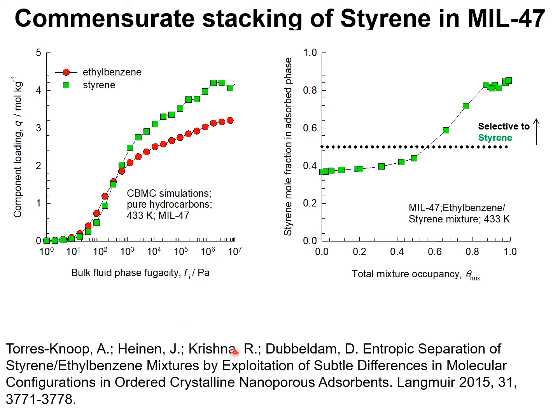The slide shows molecular simulation data to demonstrate styrene ethyl benzene separations using MIL47. These are the unary isotherms. We note that the styrene has a higher saturation capacity, and for mixture adsorption, entropy effects favor the adsorption of styrene because of commensurate stacking within the lozenge-shaped channels.